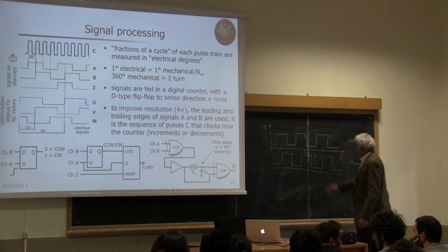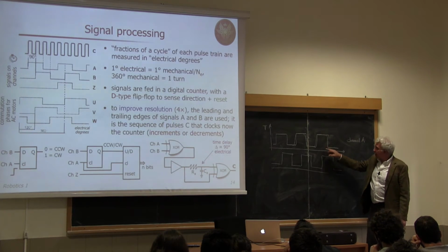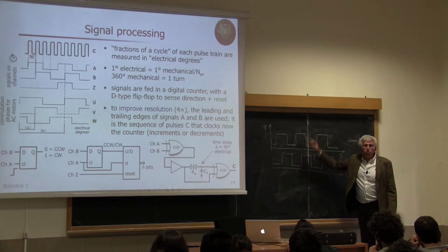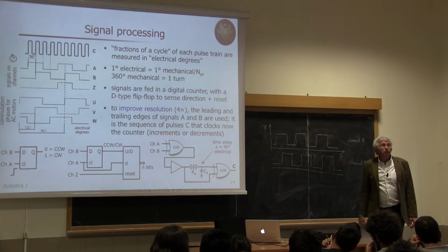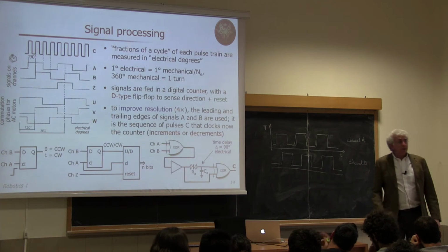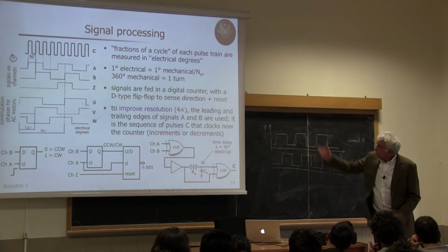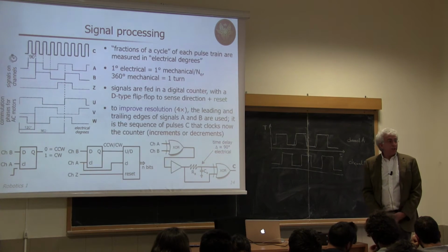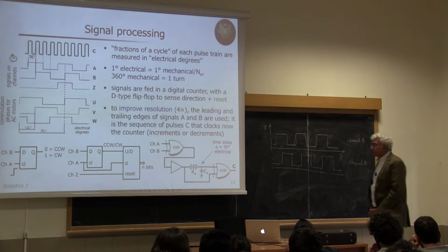Well, remember, it's related to what I tried to sketch here on the blackboard. Those signals are ideally square waves, but in fact, they are smoothed because of the timing needed by the electronics to acquire the energy of photons going from the LED to the photodetectors.